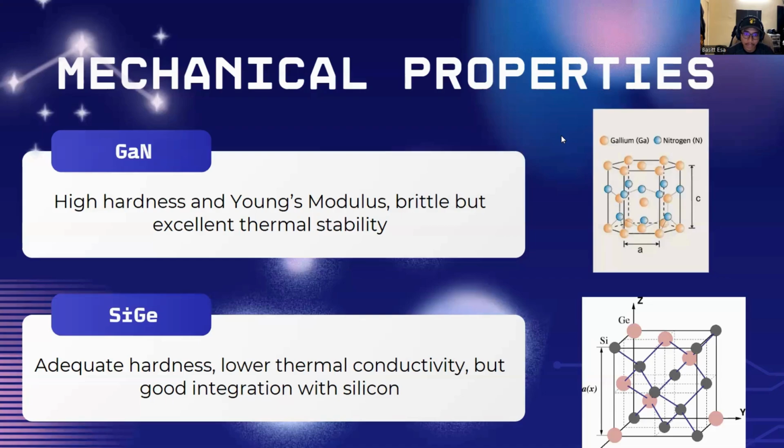better performance. As for the silicon germanium, the silicon germanium alloys have been widely accepted in radio frequency application because they exhibit good electronic properties and are compatible with silicon technology. This makes them hard enough, around 7 to 9 gigapascal, to integrate electronic devices without damage, yet remain slightly flexible. Young's modulus values for silicon germanium are around 130 to 150 gigapascal, which means some sort of compromise in rigidity has been obtained while retaining mechanical integrity.